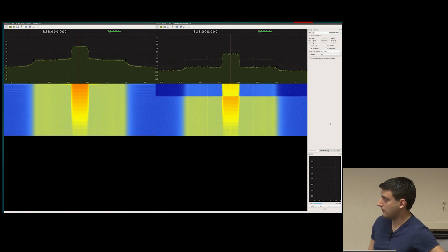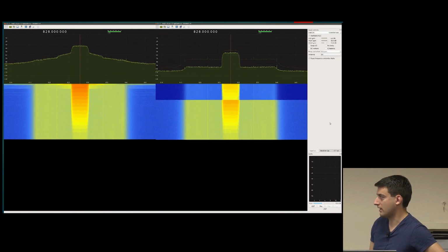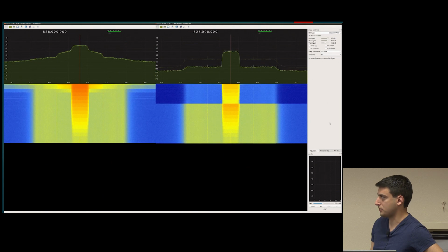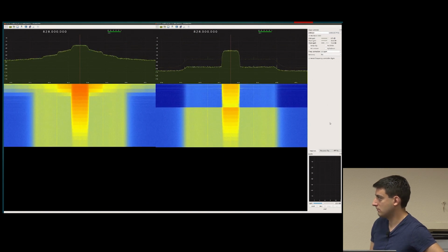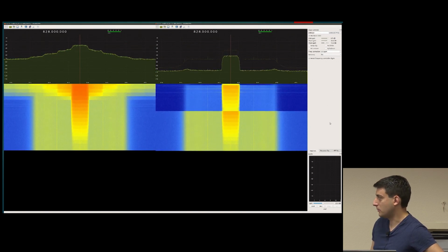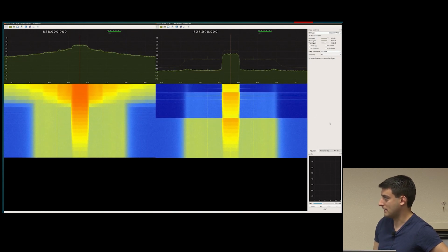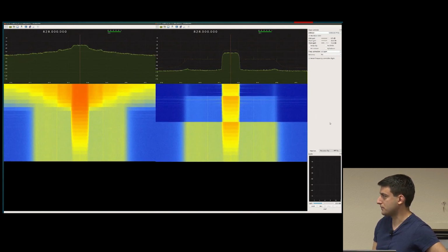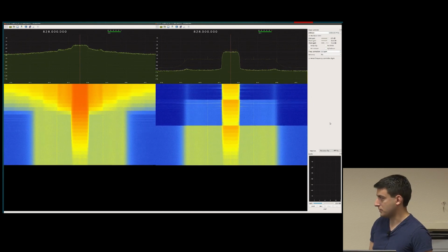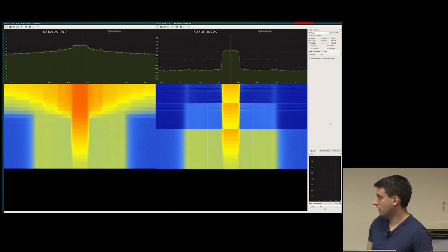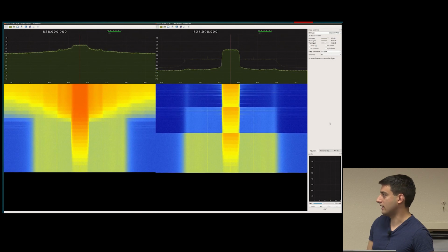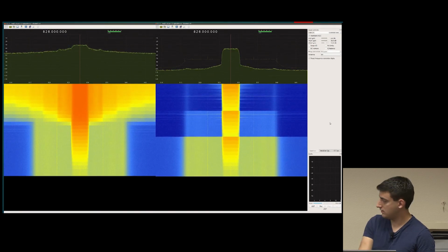the capture without the AGC will start getting more and more distorted as the spectral skirt phenomenon exhibits itself. Meanwhile, the AGC enabled bladeRF is able to maintain a really decent signal-to-noise ratio. So this is just a visual of the AGC running.